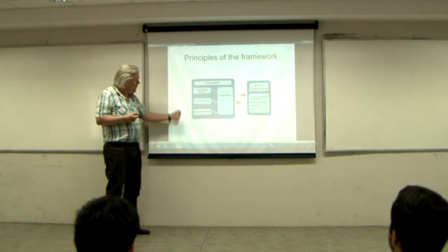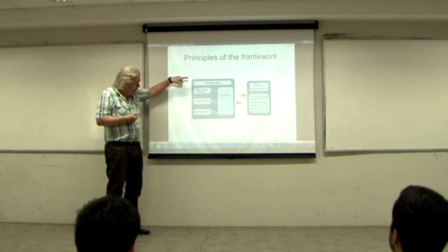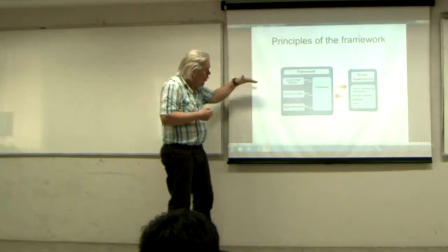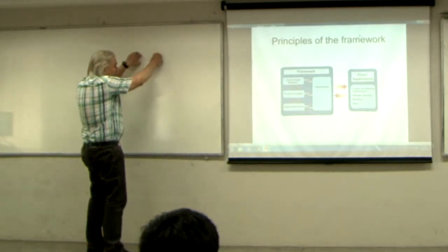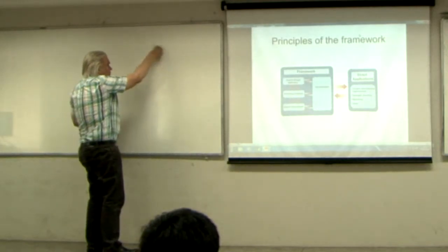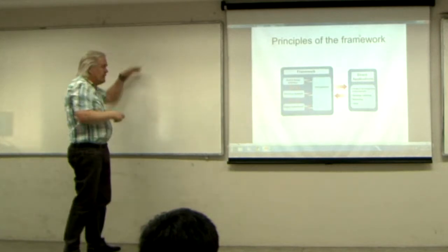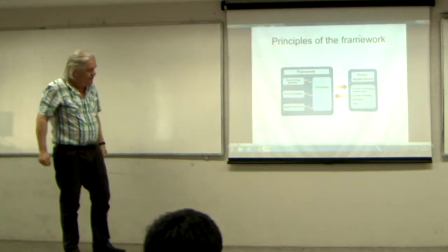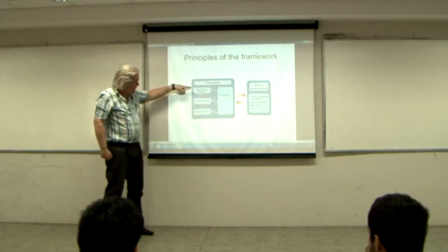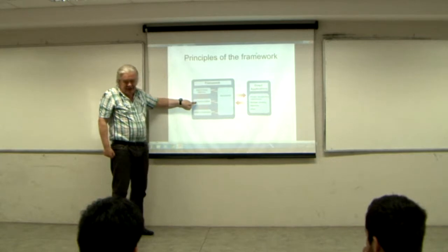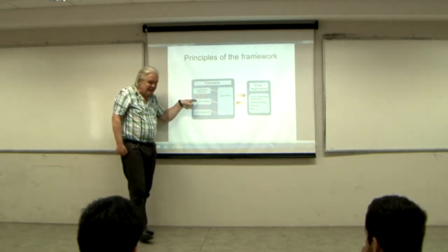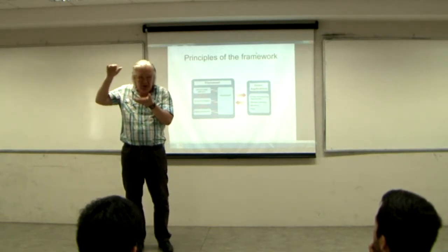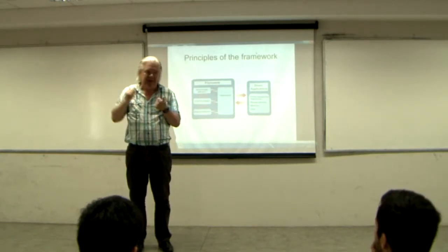And when we have calculated and decided the functional unit, we have to calculate all streams in the entire flow sheet. All streams that are connected to describe the production process from the cradle to the grave. After, we can do an inventory. And what is an inventory? This is to summarize all the emissions, all the resource use that are connected to this product.